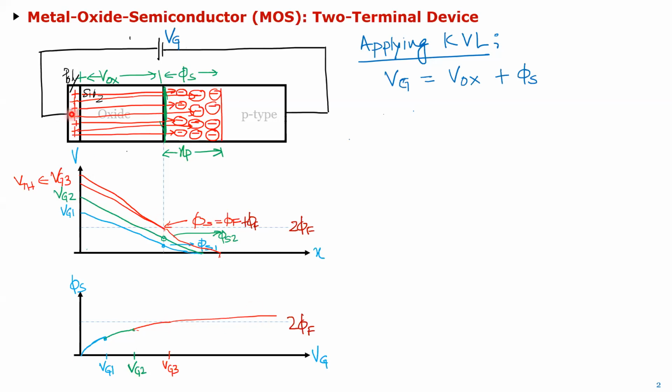So after that, whatever positive charges I put, the negative charges will form here instead of going into this depletion area. And then I can use two contacts on these two sides to actually conduct current, which we'll see later. Okay, so now the definition: this is called the threshold voltage. The threshold voltage is basically this voltage of the, I call it G because I'm just kind of building it up to the MOS device.